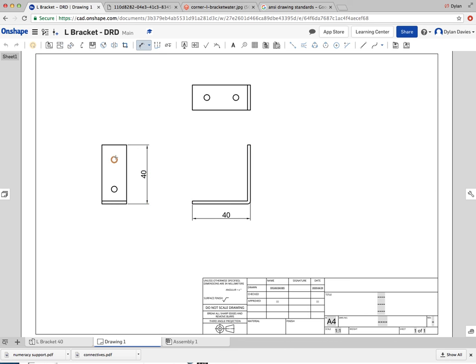And I can go ahead now and dimension the holes. So I've got a little symbol there that shows that that is the diameter. I'm missing a couple of dimensions to show the thickness. The thickness of the bar. And again, I've clicked on it incorrectly, so let's undo. I'll click on it again. Just a little bit of latency on my iMac here. And there you go. Set it to 2. And one other one, which is the width. Okay, there. And there you go. That's some of the basic dimensions.